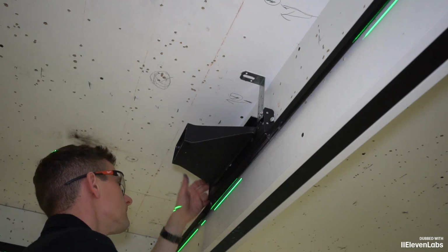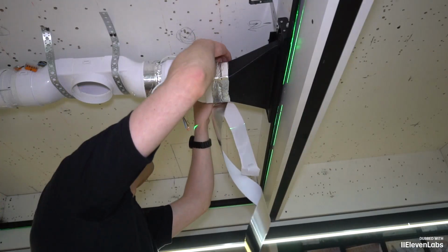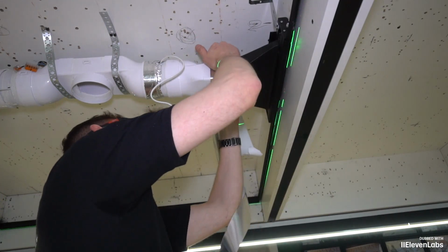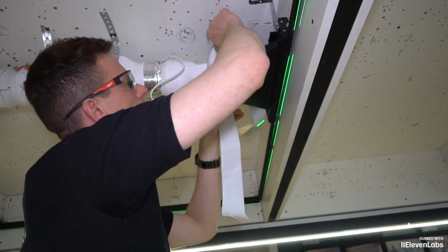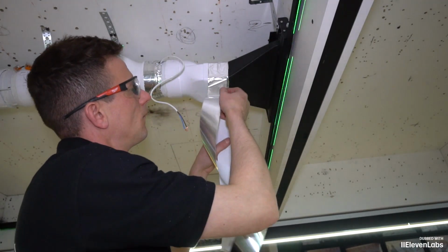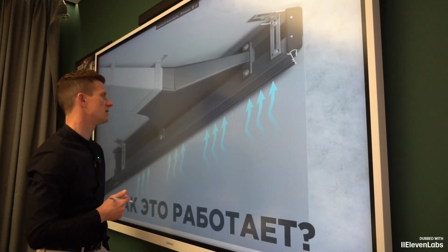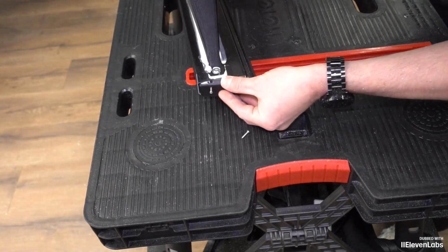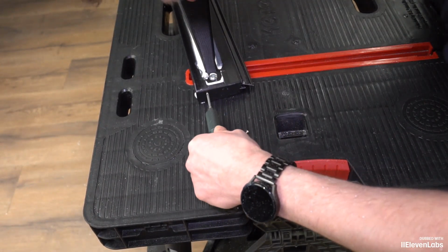This diffuser is attached to the ceiling using adjustable brackets. Alternatively, we provided an additional shelf. If your ceiling space is flat, you can attach it directly through this shelf. The installation is quite simple, the joints are perfect, and we also recommend sealing the ends with sealant. It's important that we don't have air leakage behind the trap with the ceiling.